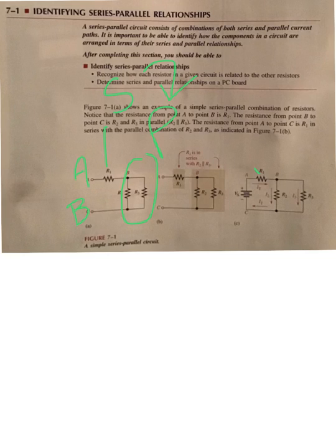So all the current flows into R1, but then it splits through R2 and R3. Whatever was up here is the total current of the circuit, and whatever's down here is split. But when it goes back to the battery, we're back to IT. So, if you will, whatever current goes in comes back to the battery. This is true of any circuit on the planet.